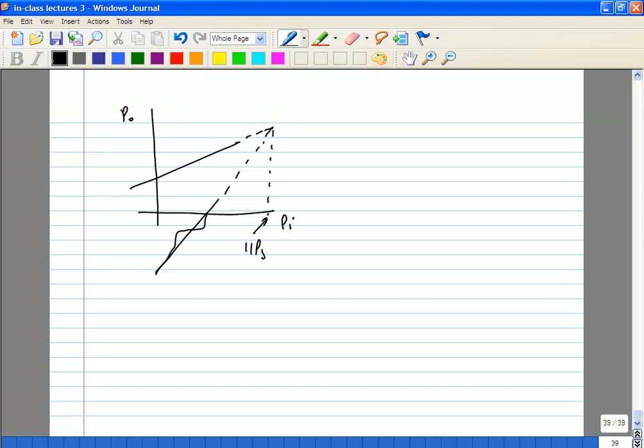purely third order. Okay, and the derivation of IIP3 and its use as the metric of choice for these kind of systems already assumes that your system has a very weak third order and your fifth, seventh order are all much weaker than that. Now if you design the system such that it has strong nonlinearities, you can make it look as if the IIP3 is very good. However, where you will get hit is actually the dynamic range of the system, which means you really cannot use it in this region. So you can use it only in this region for lower levels of power.